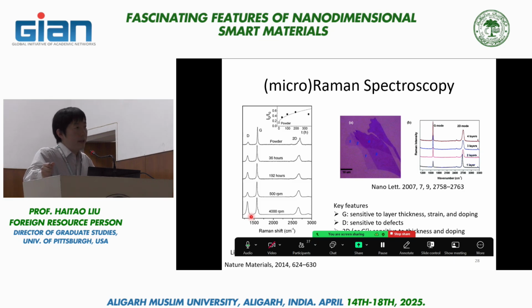In the case of graphene, you can actually stretch the graphene to a very significant degree. People have shown that single layer graphene can be stretched 10% or something like this. This is unimaginable in any other bulk material. Single crystal metal, for example, can be pulled about 0.5% and then it will break. So this is an incredible material in that kind of context.